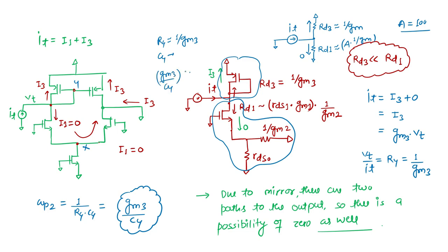Okay, so directly with the intuition we can say this, but we must have the idea of this exact calculation, what is happening at this node and why this output cap is considered as shorted. This thing is very important. Why shorted? Because we are analyzing our circuit at some higher frequencies where this node load cap is nearly shorted.